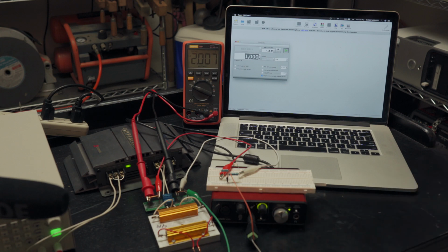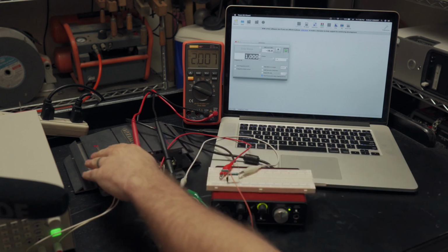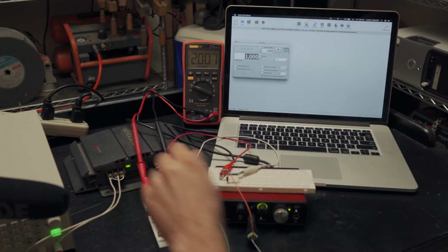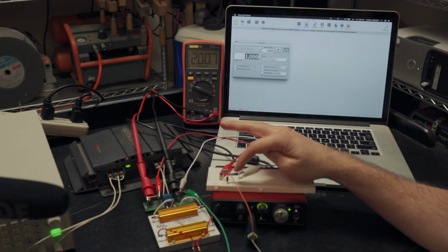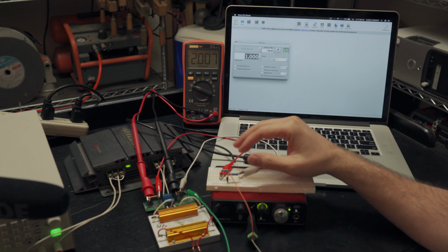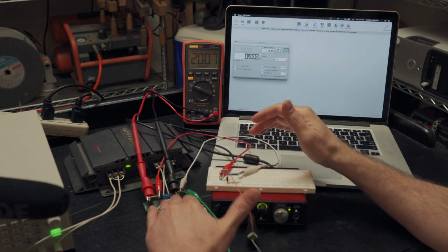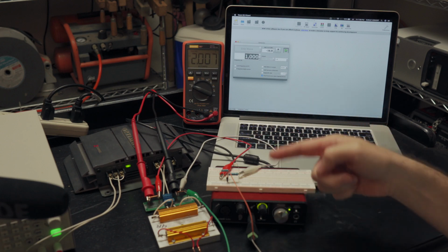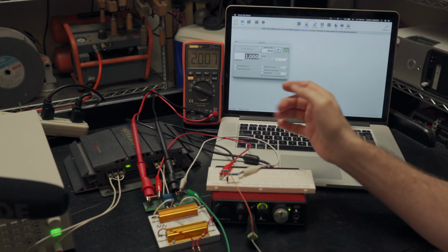Another thing you need to do, I should have mentioned this before, is that the input on a device like this is not designed to measure the output of an amplifier like this. Usually the output will clip the input before you reach the maximum power of the amplifier. And so what I've done here is I've taken a simple pair of resistors. The actual values are not that meaningful as long as they're high enough that they don't load down the amplifier and low enough that they don't create such a large output impedance from the circuit that they mess with this. So anyway, I'm using, I think, a 10K and a 1K, right?